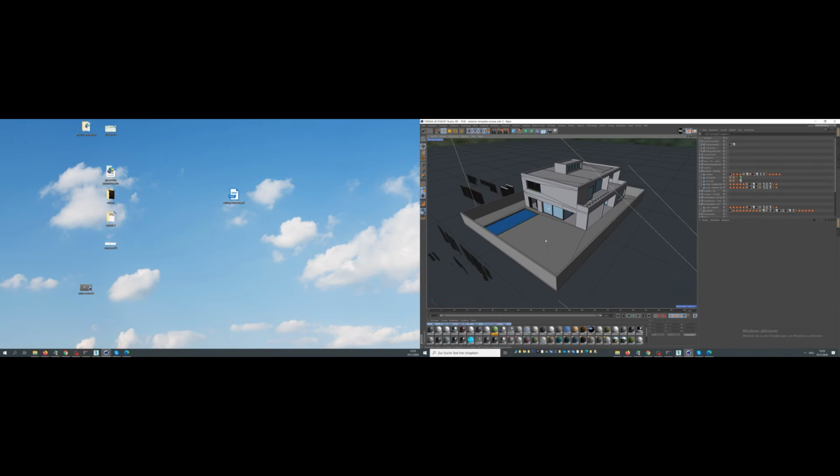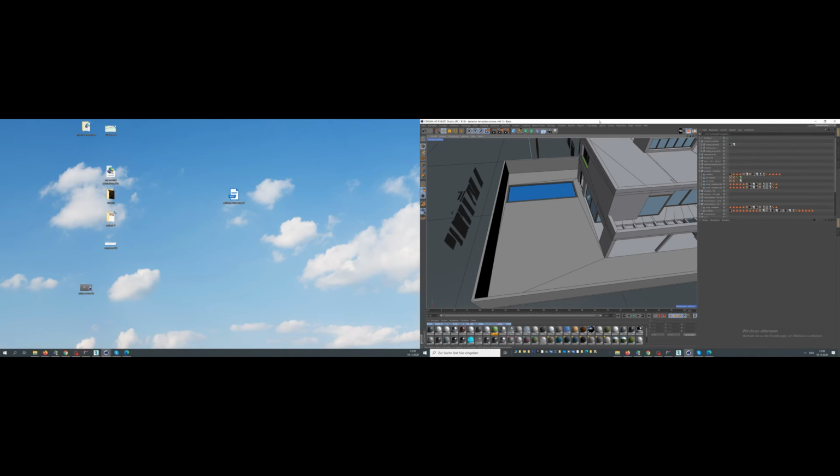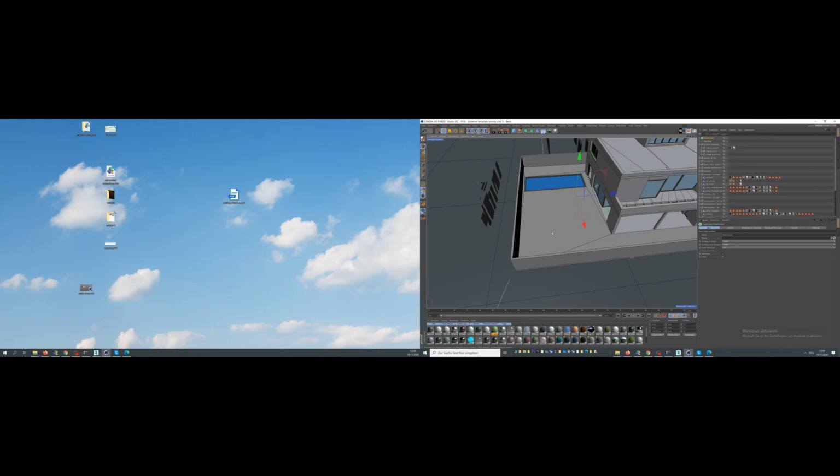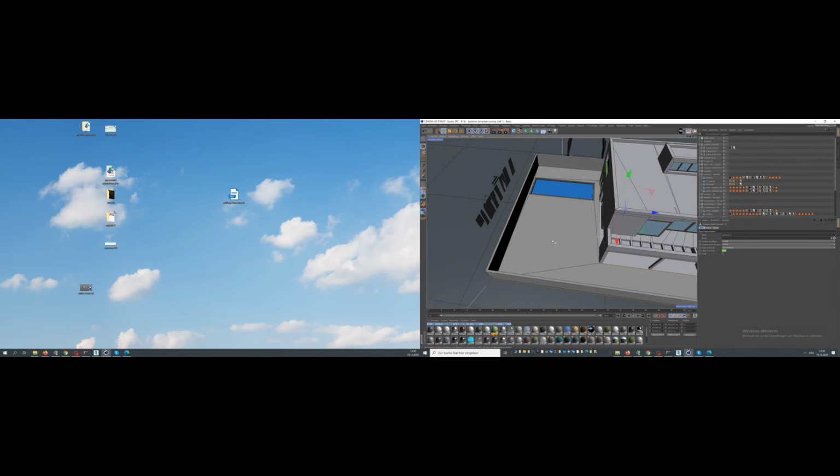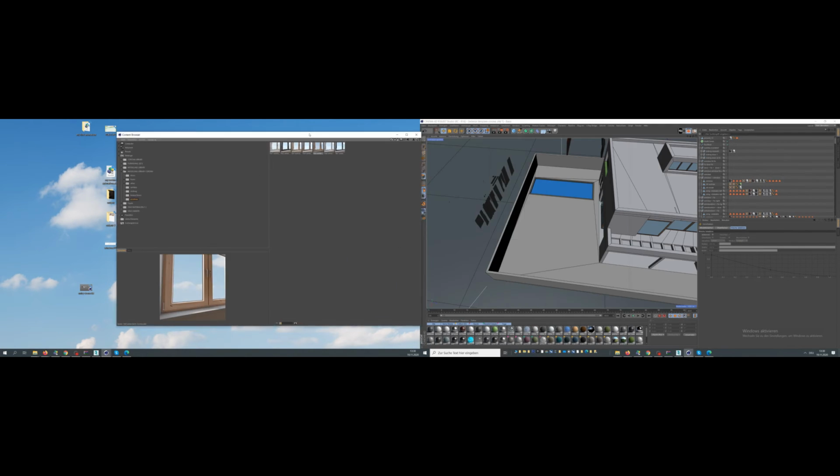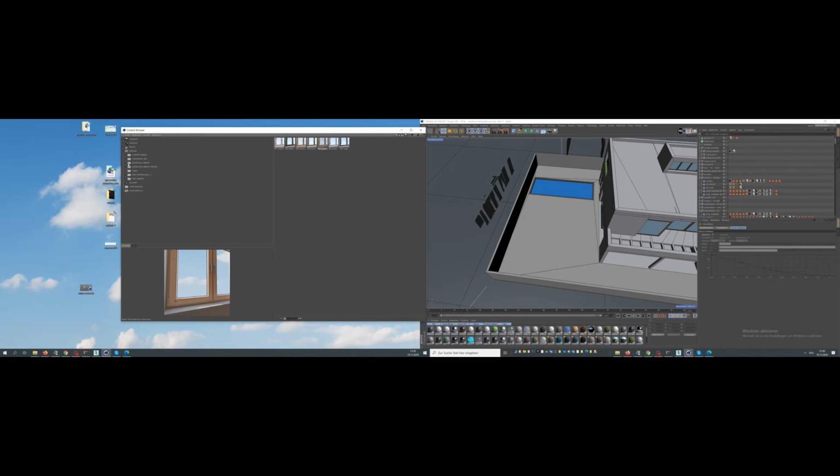And one of the coolest, newest plugins that I saw is this Forester plugin. You know it maybe from 3ds Max. We use for now only this multi-cloner from the Forester plugin, and we use it especially to make vegetation and 3D grass. So now I wanted to make, for example, some grass on those surfaces. Let us choose only that one. I selected those surfaces, and make a selection and freeze. So now drag in some from the library.